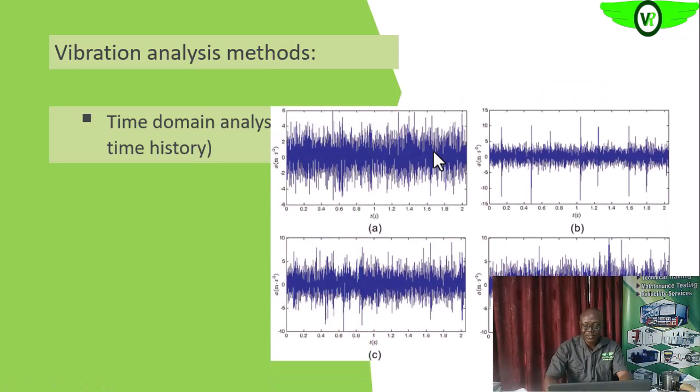Then you can have a baseline waveform and compare subsequent vibration waveforms to the baseline information.